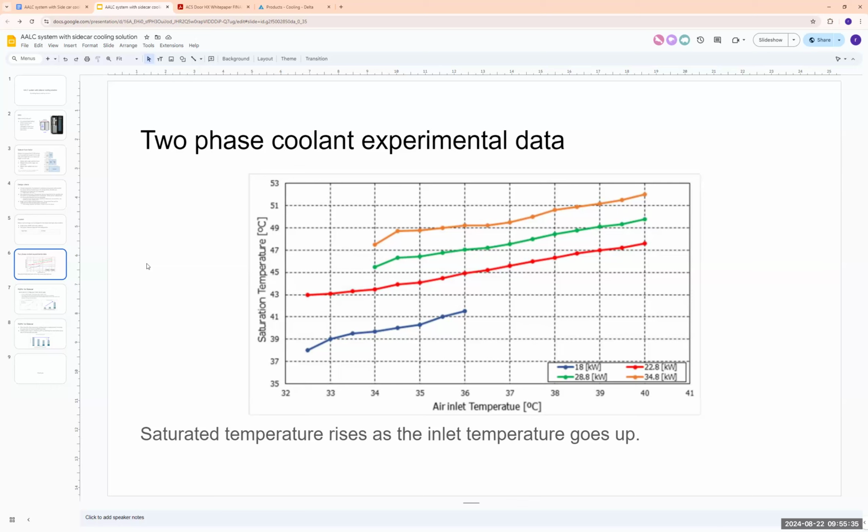You're going into too much technical detail. If you introduce microchannels, that's going to increase the pressure drop at the pump, and that's going to increase the pumping power of the whole system. But it's not the case. You can put as many channels in parallel as you want and reduce the pressure drop in the microchannel. So at least the microchannel heat exchanger is much better, because with the same pressure drop, you are able to transfer more energy because of the corrugated fins and the way they put the fins.